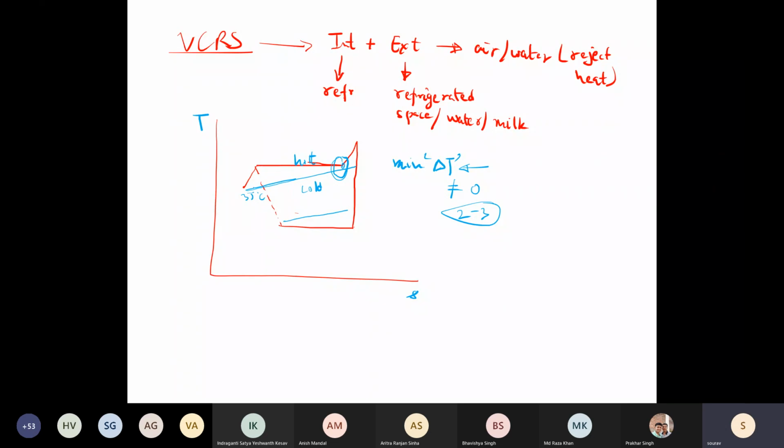Okay, please remember this temperature is not the condensing temperature. Condensing temperature is the temperature or the isotherm denoting this two-phase region. So it could be 50 or 45, whatever, based on this pinch point. So you can go up to whatever the inlet air temperature is, but you cannot go further. And hence we had discussed that we can go for an LSHX system in case we want further subcooling.